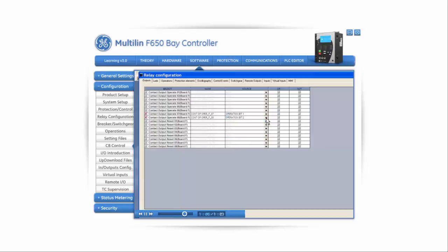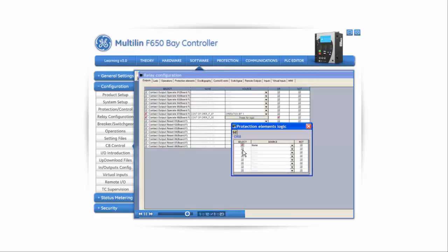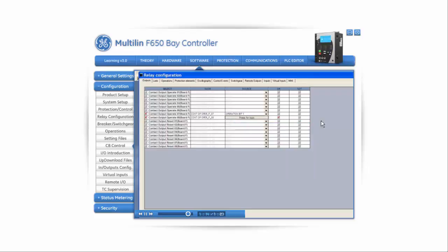However, remember that when the relay is in proper operation, the user will have to configure a logic so that the relay operates the breaker when some protection function orders it, or when an operator orders it manually. To accomplish this, check the OR or NOT columns and select the sources by clicking on the Sources column. Finally, we are ready to operate the breaker.